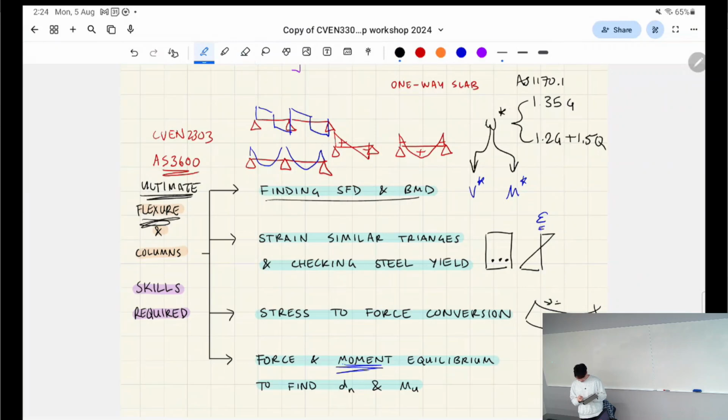If you think of these fibers, the top fibers, as it's bending, are going to be compressed or pushed together. The bottom fibers are going to be pulled apart like this, and that's where your cracks will form in concrete. So we just say that the bottom is in tension and the top is in compression. How do we express that? Well, we can express that through the strain diagram. This is a measurement of how much your beam is being pushed together or pulled apart.